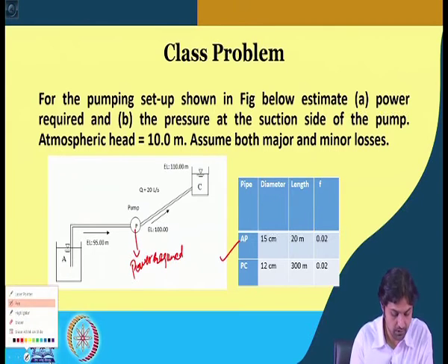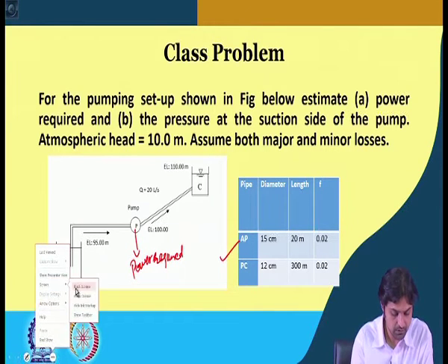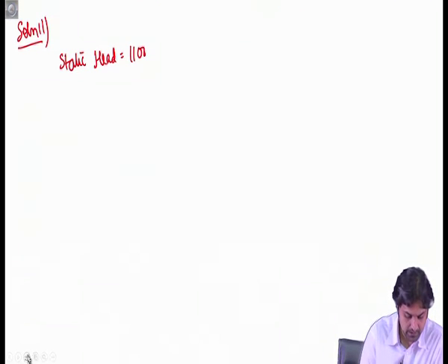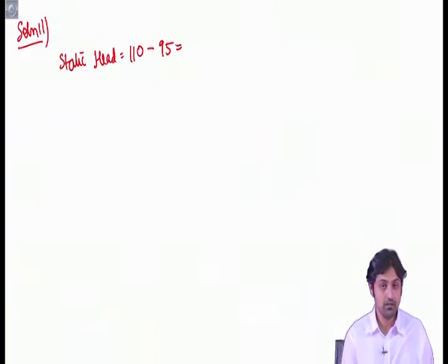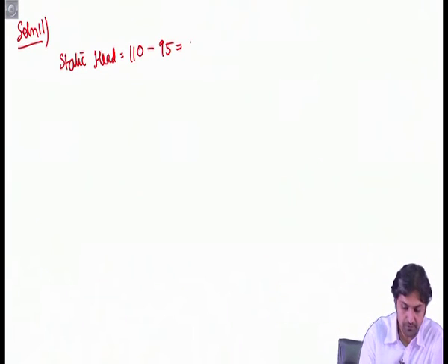So, we will continue with part A. Static head is 110 minus 95. That is the static head, if you remember the figure, and that is 15 meters.